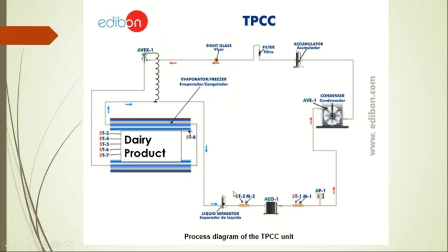So in between you can see this is the LP low pressure line, and this is the high pressure line. The low pressure line is at the suction part of the compressor, although the high pressure line is at the discharge part of the compressor. So here ST2 is installed, the temperature transmitter, which will give you the input readings in the computer. On the other hand, the high pressure reading you can easily get with ST1 temperature. So, okay, here AP1 is actually the pressure switch.